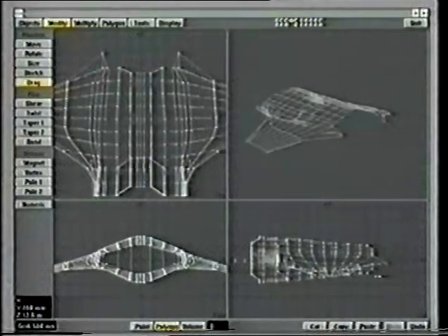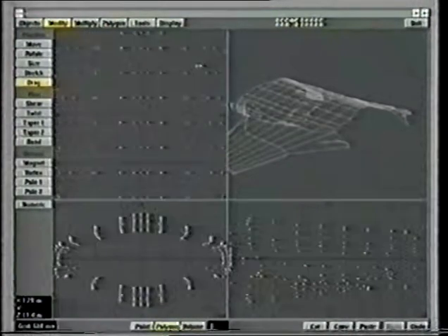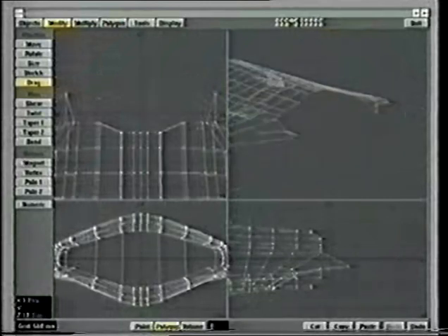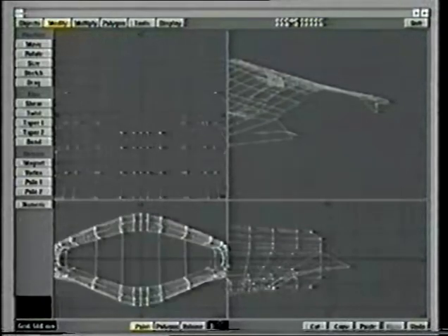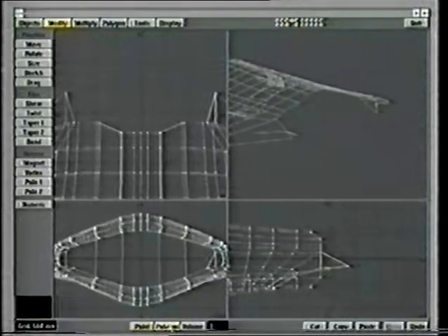You can go into point select mode. Deselect those. There's that one, and that one. Check that I've only got 3 points selected and hit the P. Check that polygon. That looks right, and the surface normal is facing the right way.